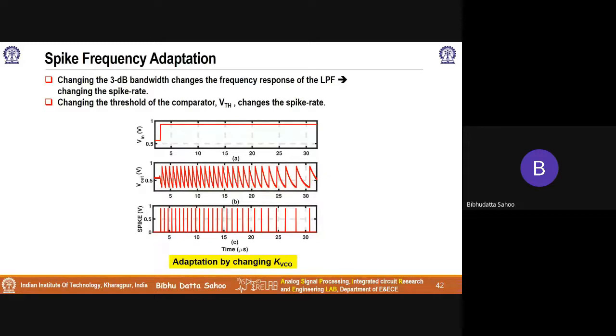For example, when we try to build, let's say, a CIFAR10 image classification algorithm on an FPGA, which is purely digital, the power consumption is pretty high, and if we go for AlexNet and VGGNet and Tiny Darknet and all, we are getting power numbers close to 2-3 watts. Sometimes it goes all the way up to 5 watts in digital. Most of the power consumption is in the memory access, because there are so many filter coefficients and all.